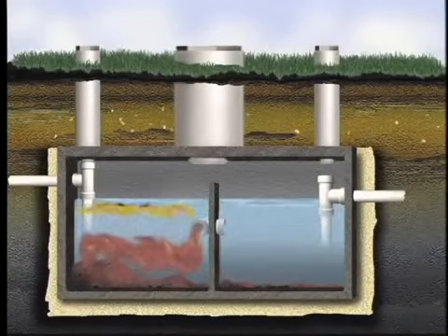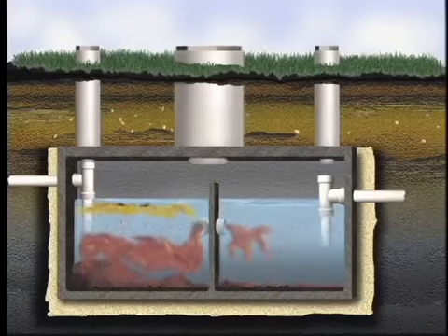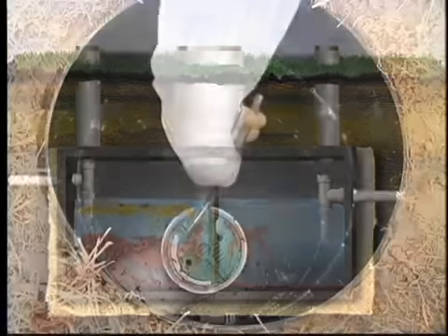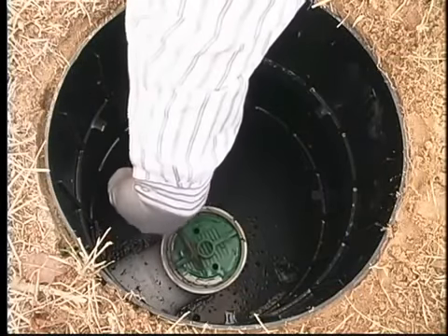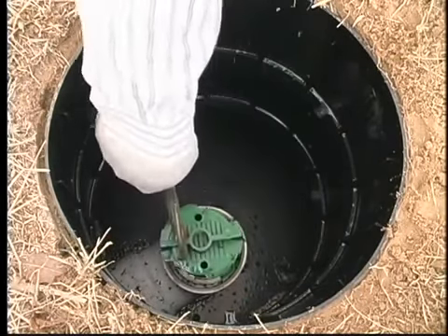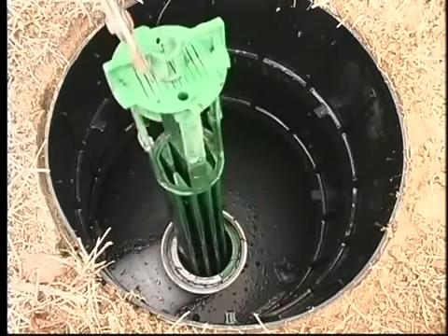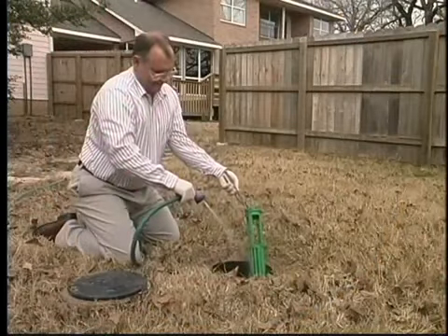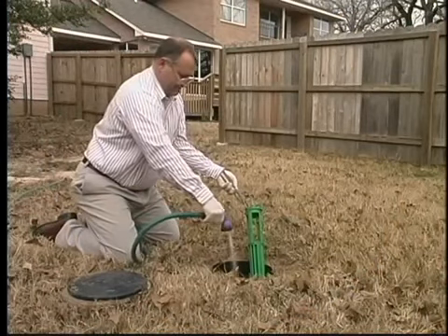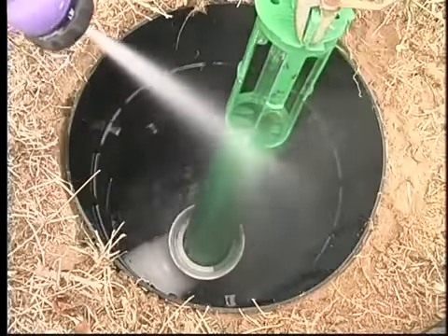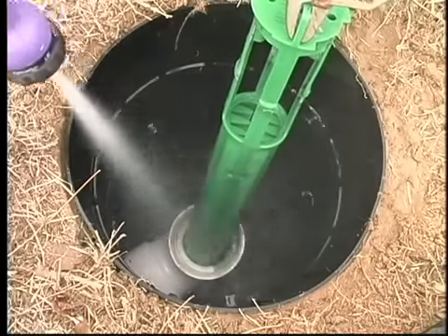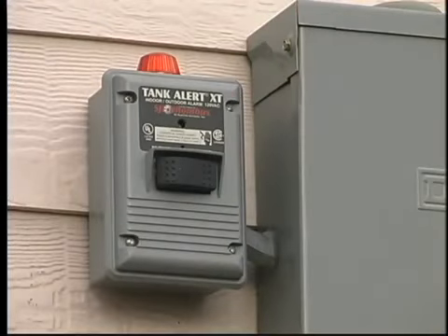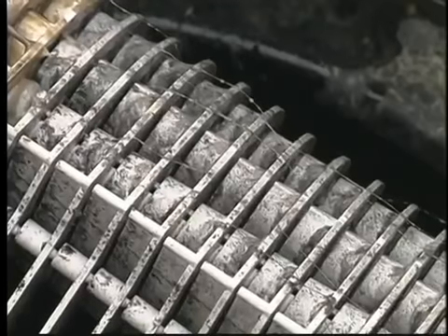Still, the majority of the organic matter, solids, nutrients, and pathogens remain in the wastewater as it leaves the septic tank. An effluent filter is used to assist in removing additional solids from the wastewater. This keeps larger solids from clogging the soil absorption field. This filter needs to be maintained periodically by removing it from the tank outlet to wash the solids off its surface and back into the tank. An alarm system will alert the homeowner if the filter becomes plugged and the tank water level begins to rise.